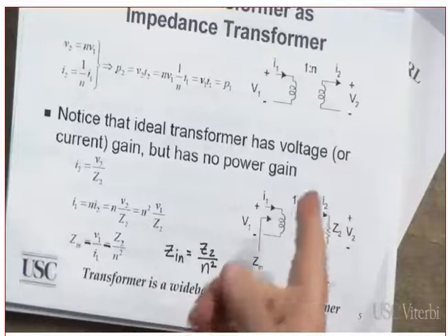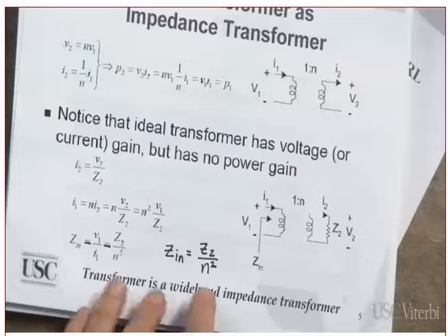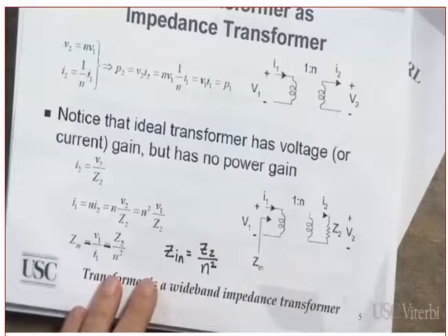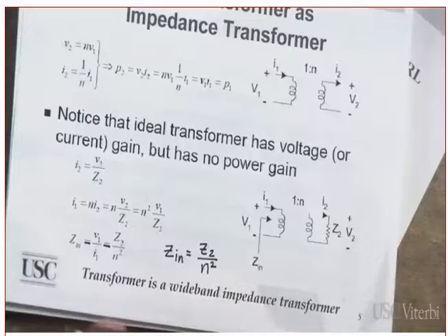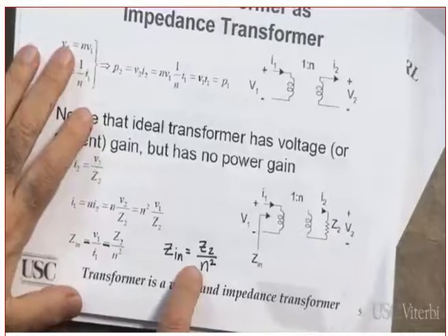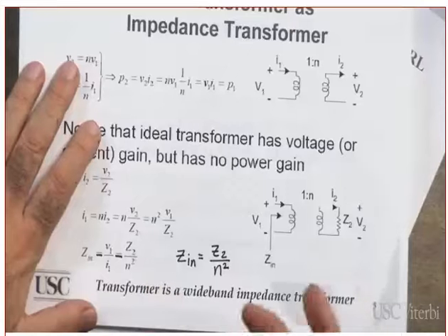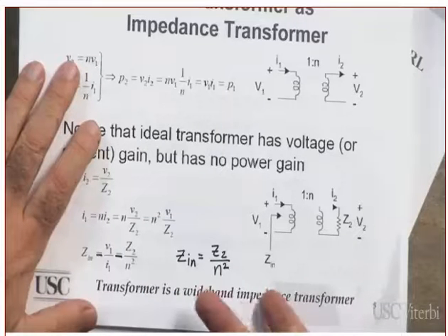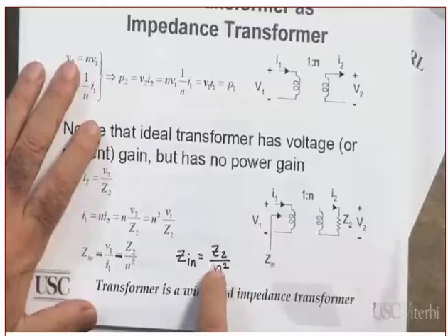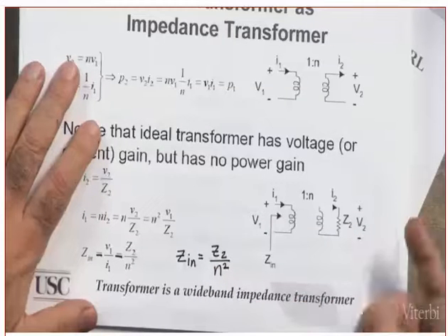I want you to tell me what is the problem with this circuit using a transformer. The number of turns, the N to 1, needs to be what? In other words, listen to me. Let's assume that you were given Z2. What does this tell you? It tells you Z2 over Zn should be equal to N squared. Did you get this or not? Which means the only thing that you have control of is what? To achieve matching between Z2, why do we call it Z2? This Z2 is ZL. Yes or no?